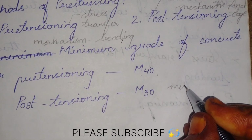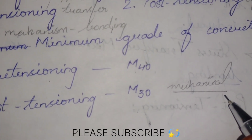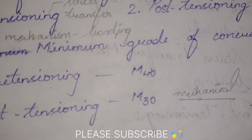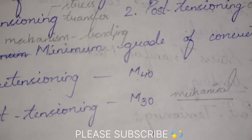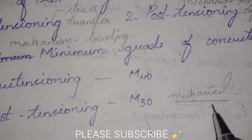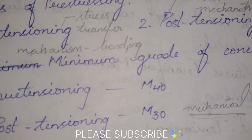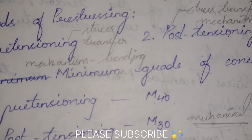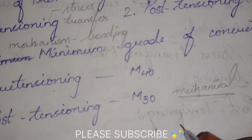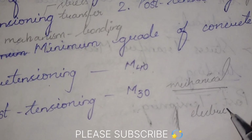As you all know, the first one is mechanical. When I say the mechanical system, this means we are using some weights, with or without a lever arm. Generally we are using pulley blocks and screw jacks. So mechanically we are inducing this prestress. Next, let us see the electrical devices. Here we are using steel wires or deformed bars that are electrically heated and anchored. So here we are using the anchorage system which is electrically operated.